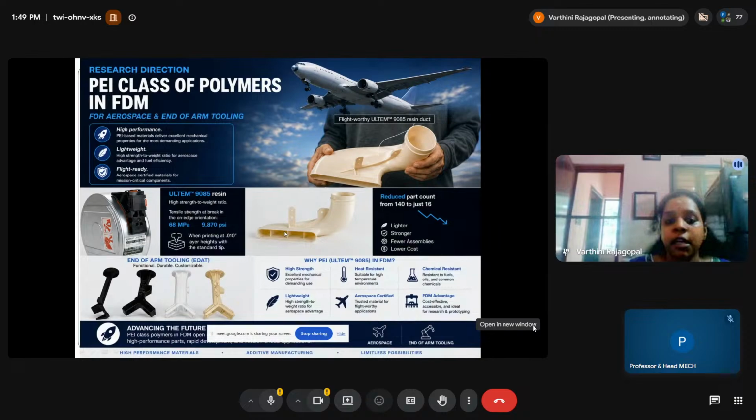Yeah. So I was talking about the profiles of scaffolds made up of calcium and hydroxyapatite. So how to build that? I was saying that FDM is not restricted to filament usage, right? Instead of filament, here you are going to use a paste. Every 3D, you would have heard the term bioplotter, right? A bioplotter will be very, very costly because it uses pneumatic controlled extrusion, right?